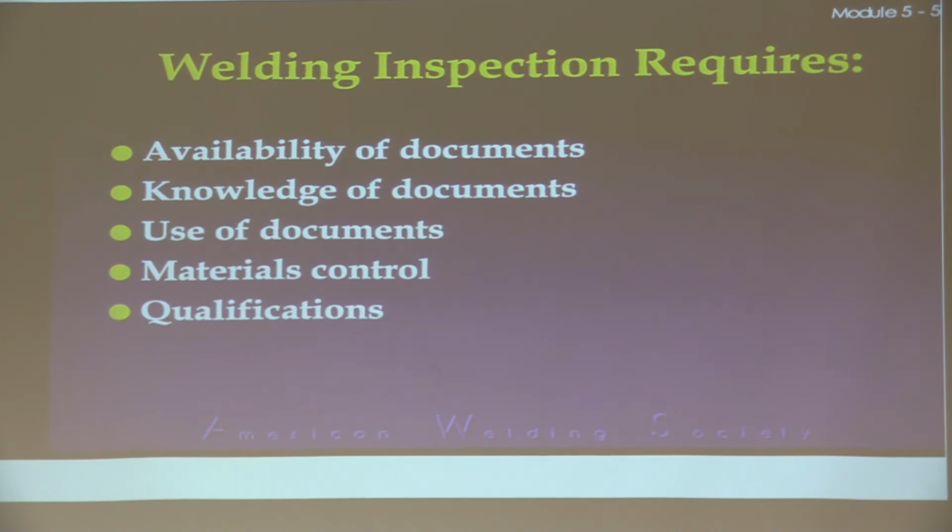Page 5-31, left-hand column, second paragraph down. It starts out, it says the finished test coupon is then marked to identify according to the welder's name, test position, top of the coupon in case of a pipe welded in 5G, 6G, and 6GR positions. So most of you have been through this with me. There's not much different there. But the documentation at this point and the reference is very important.